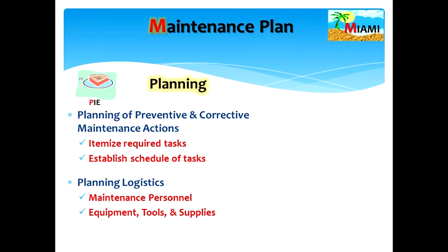Third, the maintenance plan shall have plans for preventive and corrective maintenance tasks. We will talk about those later. Also, the frequency and schedule of the maintenance tasks are required. For example, the basin may need to be inspected quarterly, and the sand layer of a sand filter may need to be replaced every 2 years.